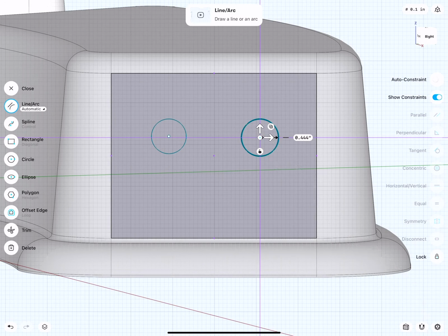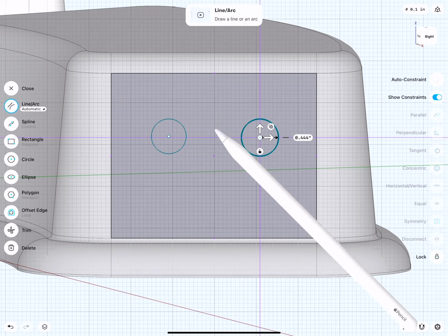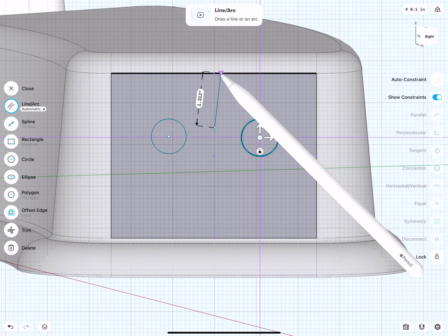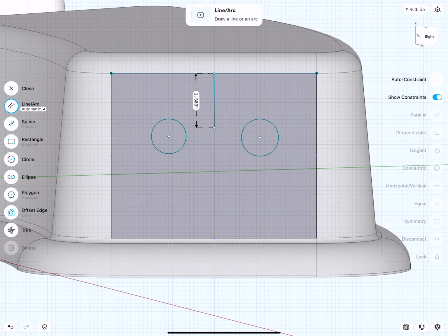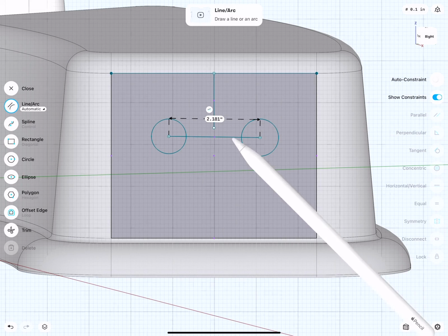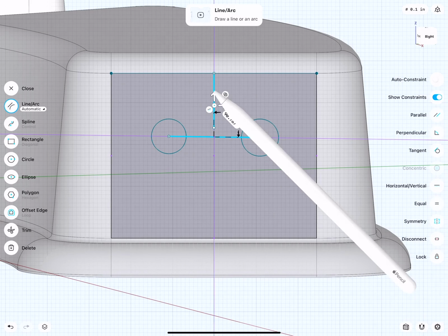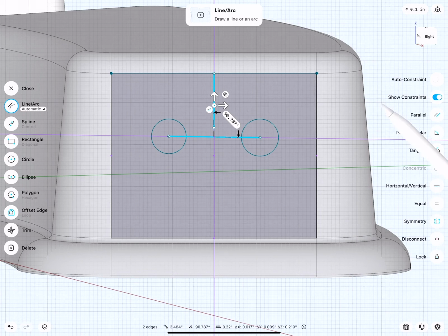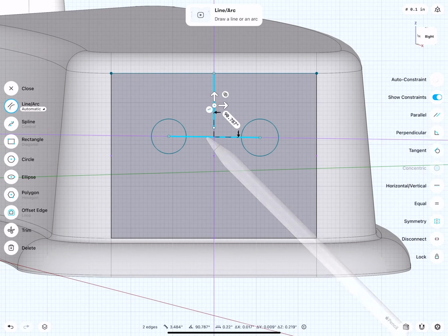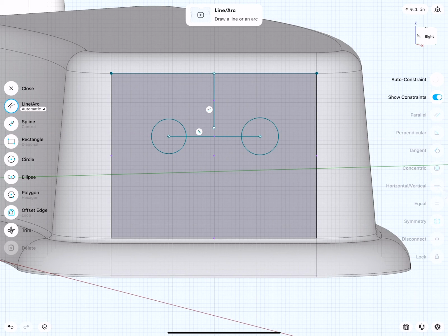You take a look at the top, you see there is an edge plus a midpoint. There I snap to the midpoint. I make this horizontal and draw a line this way. Sorry, I meant this line I made vertical, because this line I will make horizontal.